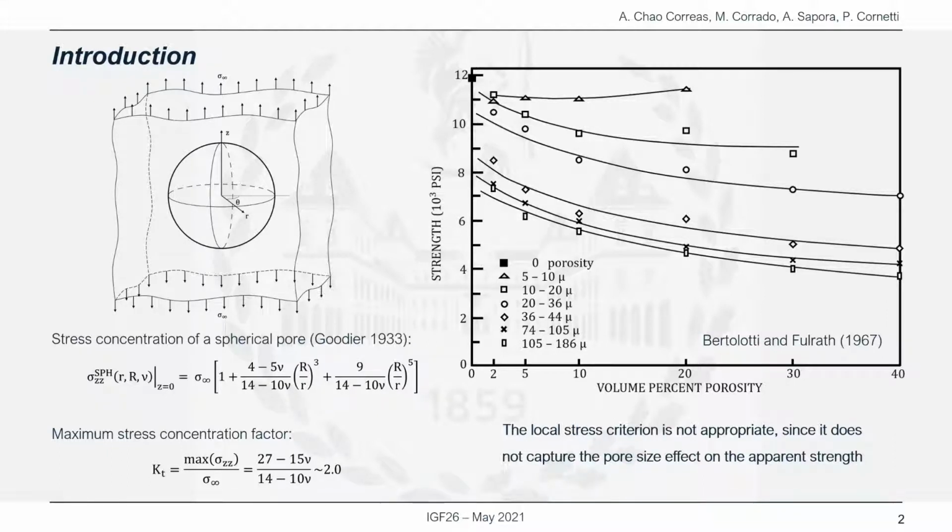It is also known that the size effect is a particularity of linear elastic fracture mechanics solutions, which in essence are energetic balances versus the material fracture toughness. However, in the considered case, this formulation is not straightforwardly applicable due to the lack of a pre-existing crack, which, according to the energetic balance of linear elastic fracture mechanics, would lead to infinite strength predictions. Thereafter, other applicable theories have to be, and will be, presented.